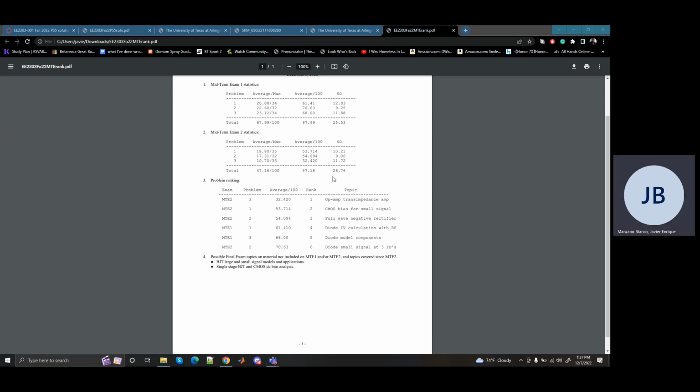I do this because now when I introduce an input signal to the amplifier, it'll move relative to that new bias point. So now these negative parts of the signal show up still. I'm getting the full signal at the output, just shifted up. And the way that I can separate them is with these decoupling capacitors.